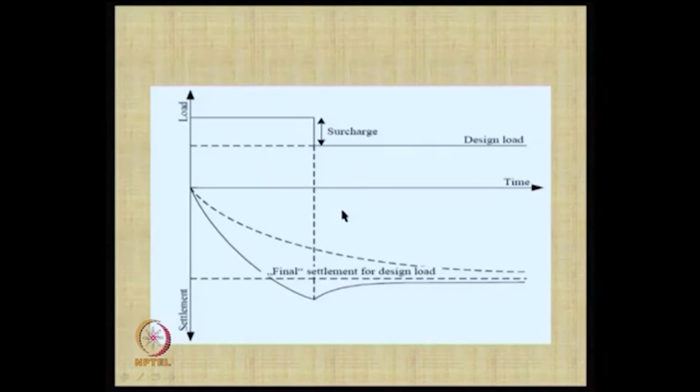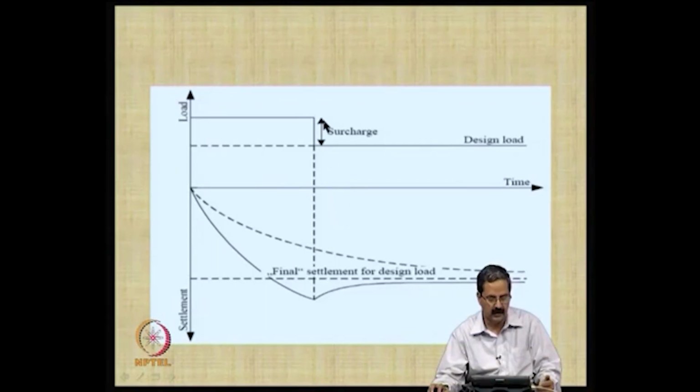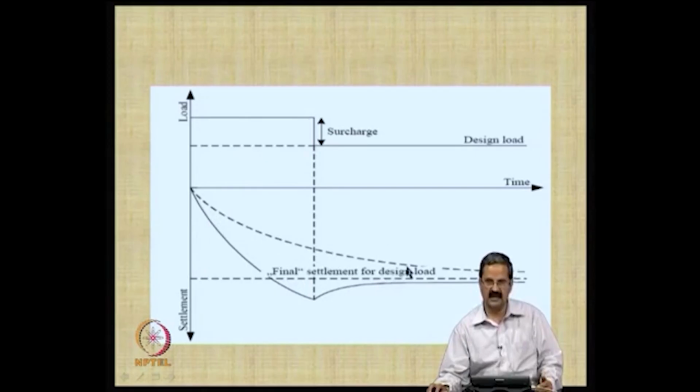So, as I just mentioned, the advantage of preloading or any of these techniques is that we try to accelerate the process of consolidation into a very short time, say maybe less than a year, to see that the subsequent settlements are going to be minimal. Like this is the final settlement for the design load. You see that to reach that settlement level,